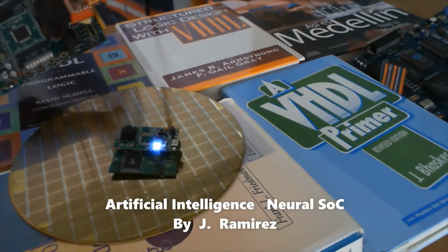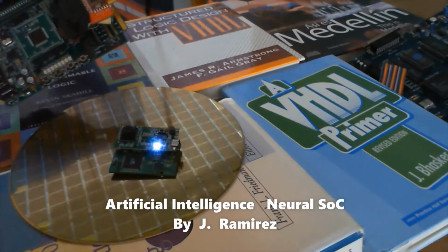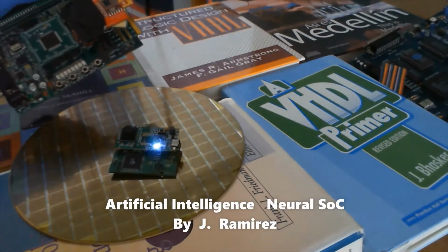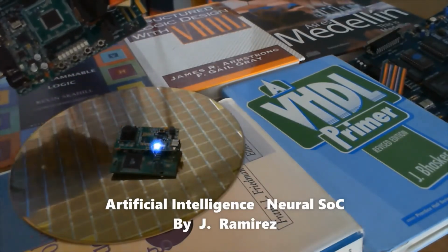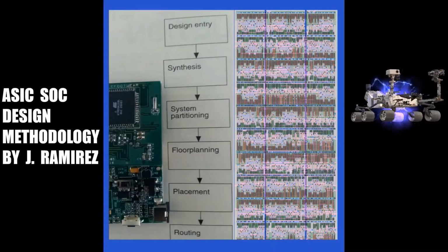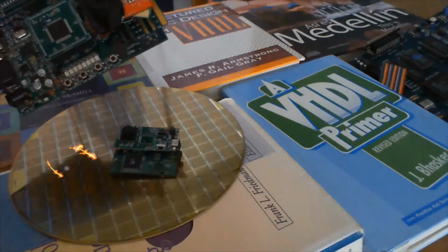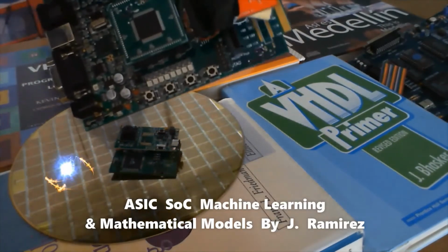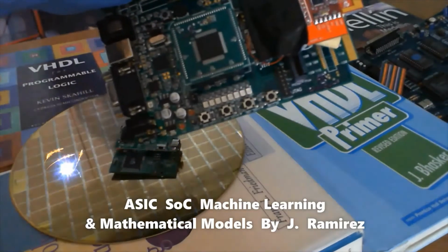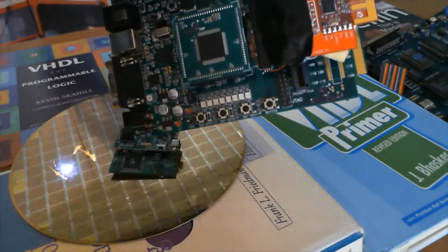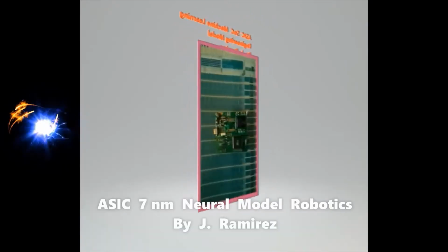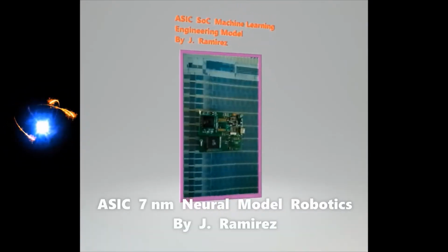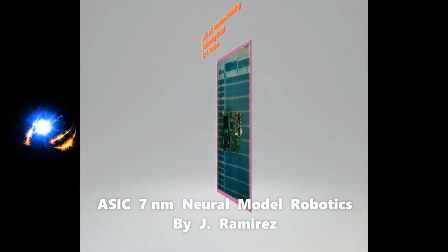My choice of synthesis and timing verification for this project was Design Compiler. So two separate mappings were done. One mapping was performed during test insertion. The software model operated on a single clock. The timing model reflected the correct timing and load values for the actual LSSD macro.